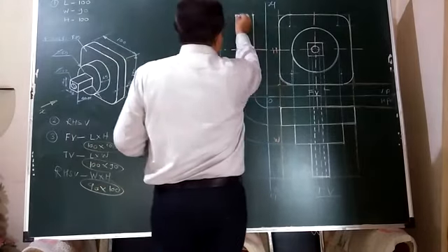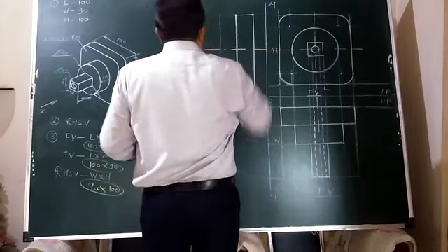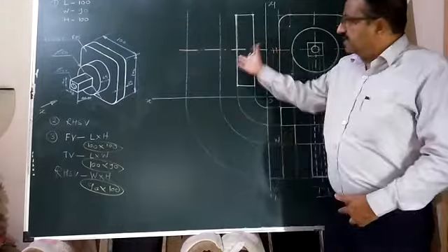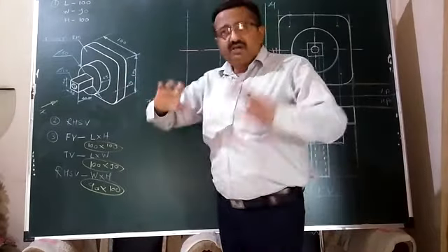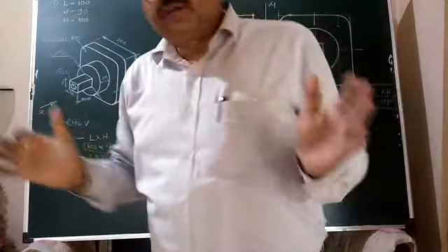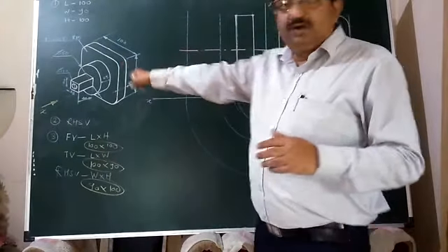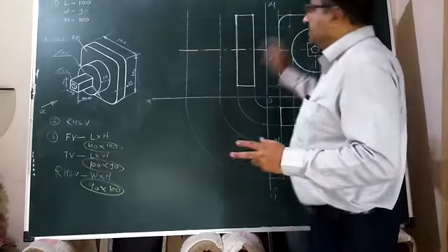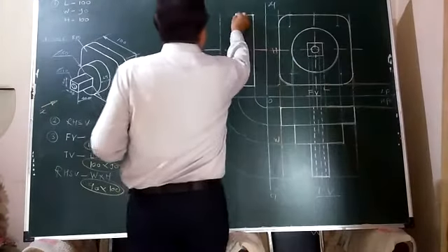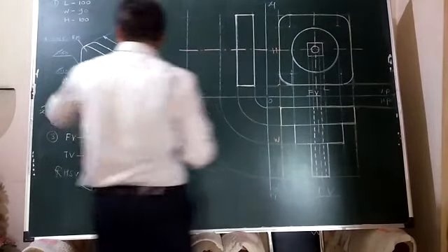Inside, those curvatures will not be appearing, only a vertical rectangular strip will appear like this. Again these corners, which are quarter circular, will give that image of quarter circularity in front view only, not in top view, not inside. So only a strip will appear like this. Okay, this is about this right extreme square plate of 100 by 100.